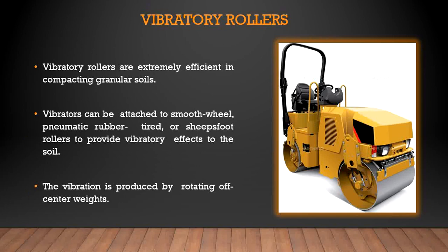Next is vibratory rollers or vibrators. These are vibrating units of the out of balance weight type or the pulsating hydraulic type. Such a type is highly effective for cohesionless soils. Behind retaining walls where the soil is confined, the backfill much deeper in thickness may be effectively compacted by vibration type of compactors. A few of these types are vibrating drum, vibrating pneumatic tire, vibrating plate, vibro float, etc.